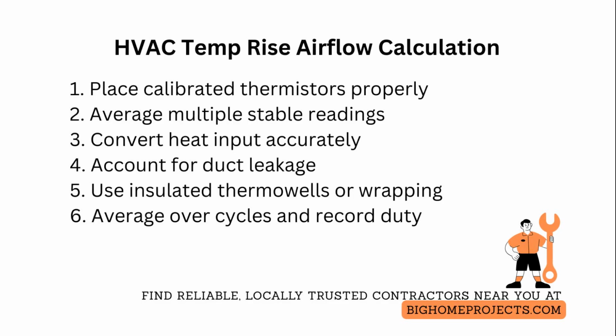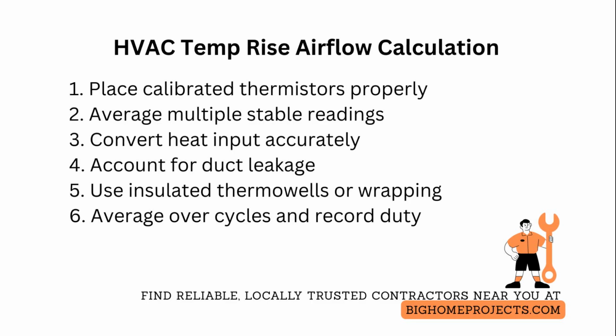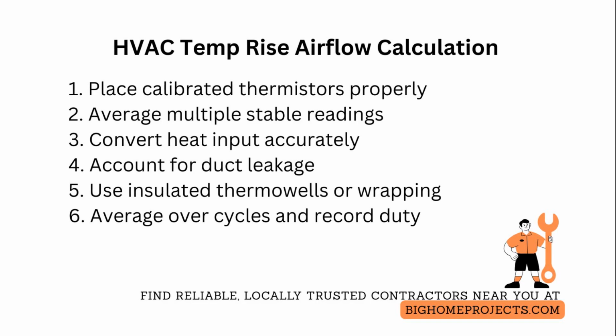Log timestamps to pair with heat input measurements, since fuel inputs can vary with firing cycles. If the system cycles, use longer averaging windows and record on/off-cycle duty to normalize the effective heat input.